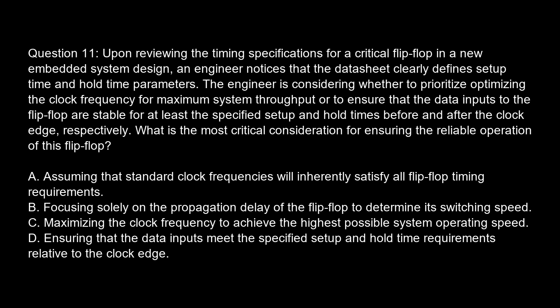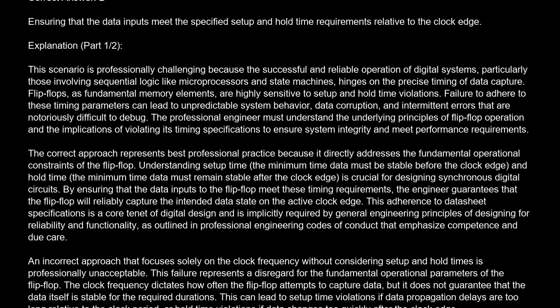Option A. Assuming that standard clock frequencies will inherently satisfy all flip-flop timing requirements. Option B. Focusing solely on the propagation delay of the flip-flop to determine its switching speed. Option C. Maximizing the clock frequency to achieve the highest possible system operating speed. Option D. Ensuring that the data inputs meet the specified setup and hold time requirements relative to the clock edge. The correct answer is D. Ensuring that the data inputs meet the specified setup and hold time requirements relative to the clock edge.